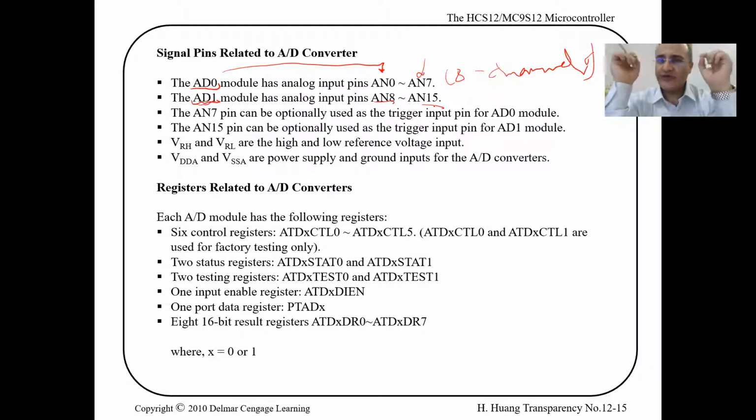At a single point of time, you can be reading one channel from here and one channel from here, but because you can switch real fast, and most likely you wouldn't need to read the temperature more than once or twice a second, you don't need to read it every 10 microseconds. So that gives you more time to switch between channels.